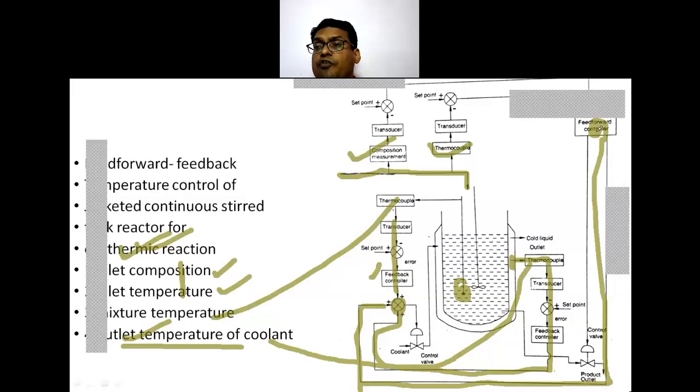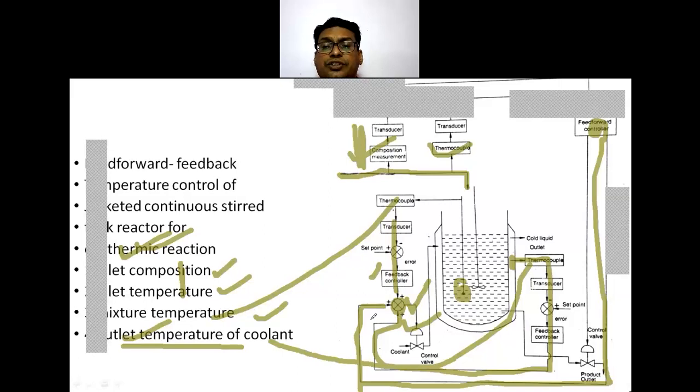The feed forward controller is concerned with the inlet composition and inlet temperature. So this comparator receives three signals: one from the actual mixture temperature, the second from the outlet temperature of the coolant, and the third from the inlet composition and temperature.